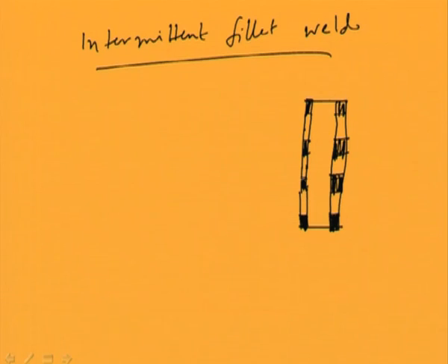In place of riveting, we are making welding at a particular pitch distance, at a particular interval. So the calculation will be similar, right? Now this is called pitch, the center to center distance. Now let us solve one example.